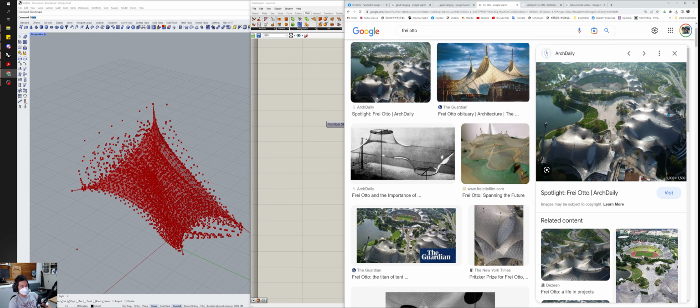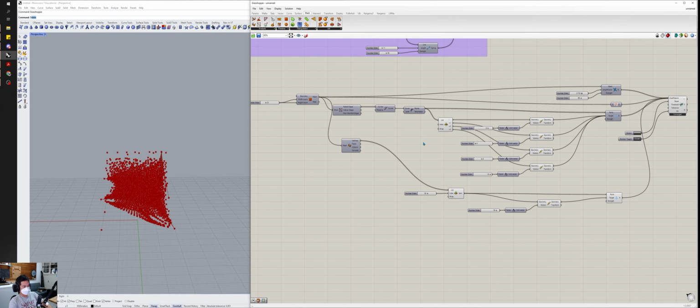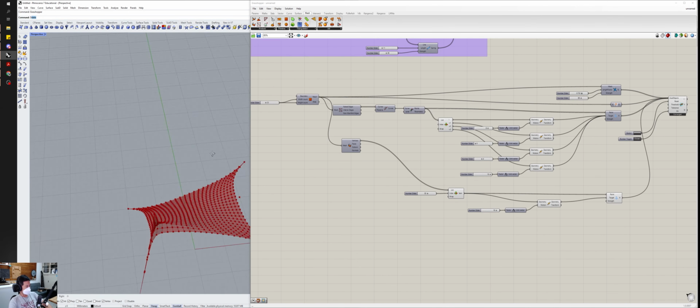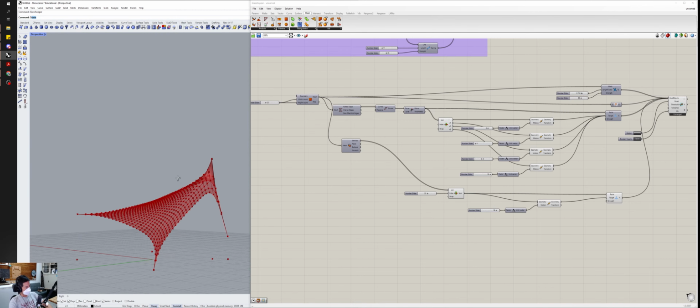And when you run the simulation, it should find the shape or outcome of what happens if you anchor those points and you push those points up, etc., right? So again, this is how you could go about finding the overall form based on certain characteristics that you input, using things like edge lengths for spring, as well as defining anchor points, right?